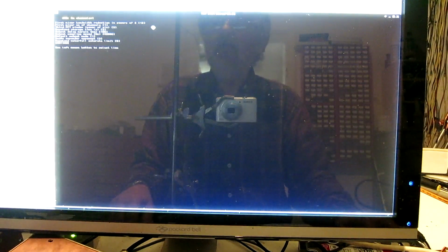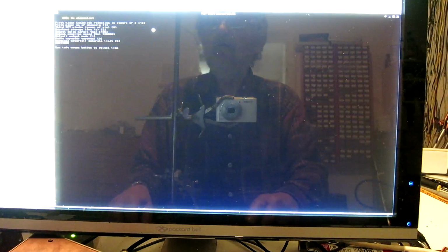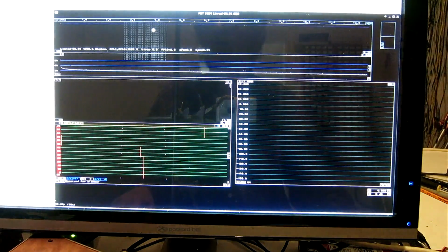And by default, Linrad selects this very high bandwidth reduction because Linrad believes that I'm using a bigger transform, which I cannot do here at this rather high sampling speed, but that will be changed with some coming version of Linrad. And this window, best to use 8. Then enter, and here we are.